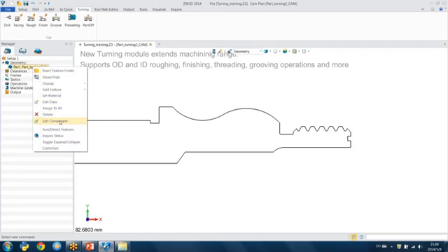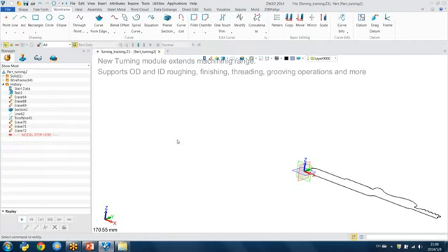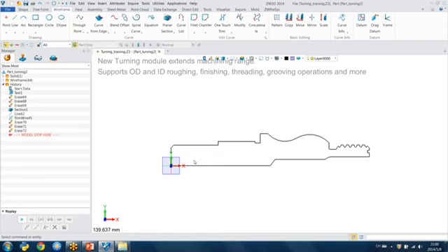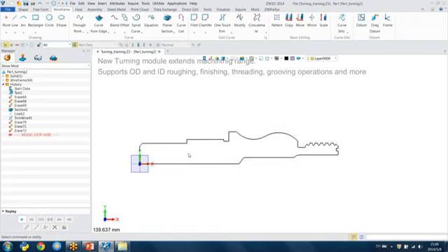If you want to change the part, you can right click on the part and choose edit component. You will go back to the part. Oh, the slot disappeared. It means it's just a refresh issue, I think.